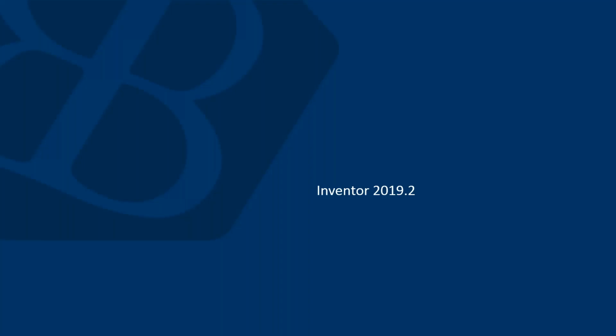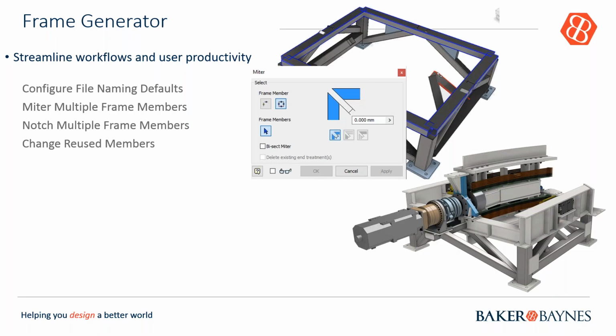All right, Inventor 2019.2. There were also some really nice enhancements here. One was to the frame generator. So the frame generator contains the following performance and productivity enhancements that have been enhanced in 2019.2. And one is the application options. The file tab has a new file naming default section for frame generator. So I know I have had a lot of questions around file namings in there. In 2019.2, you can actually edit those naming functions in there.